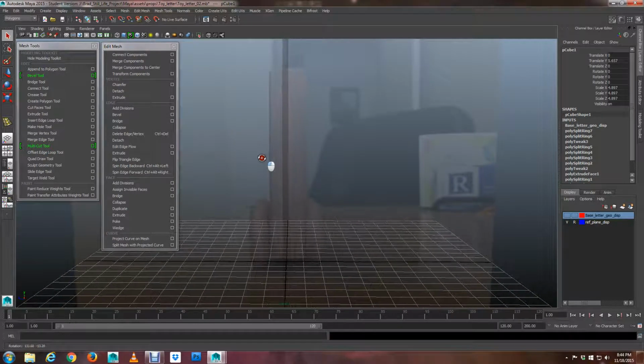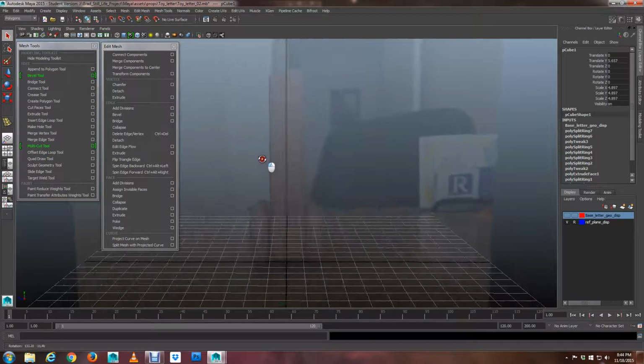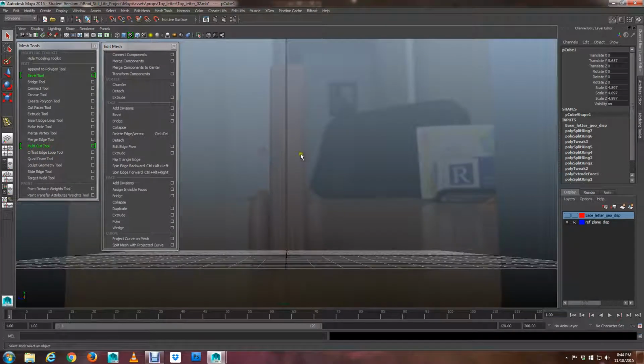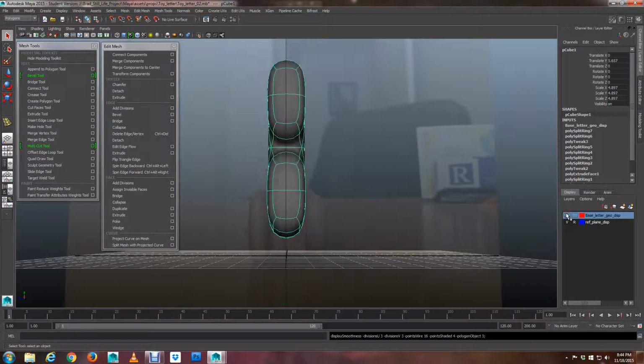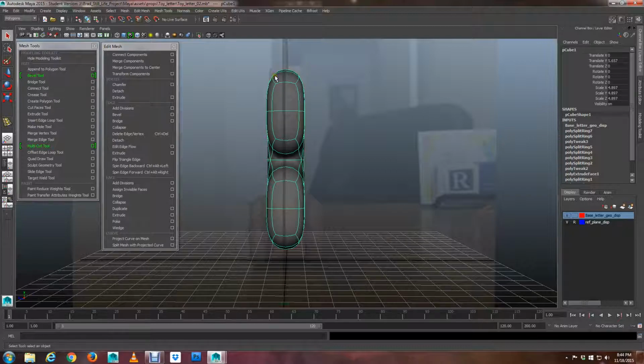It's really square from the side. You can see it's pretty square, right? And when I open this up again and I hit smooth, well, my B isn't so square, is it? So why is that? Well, we need to crease the side edges of this.